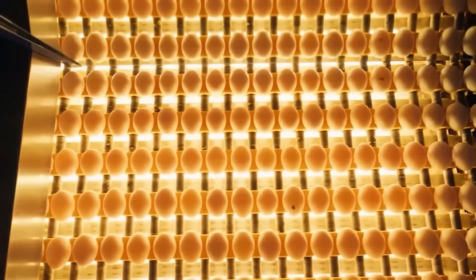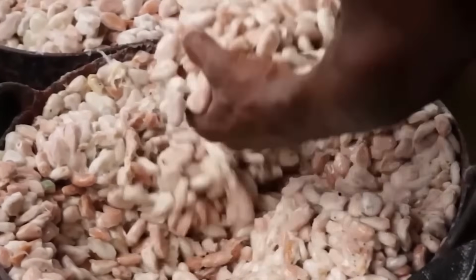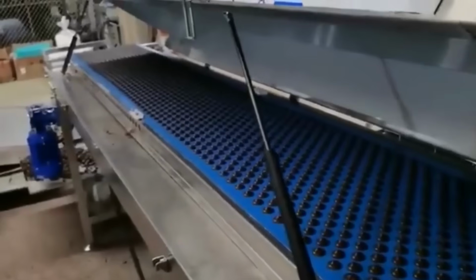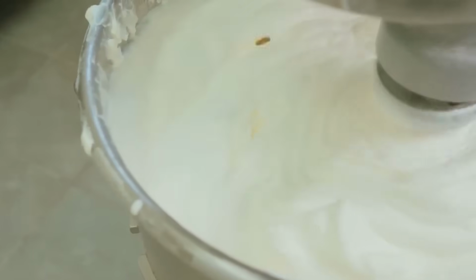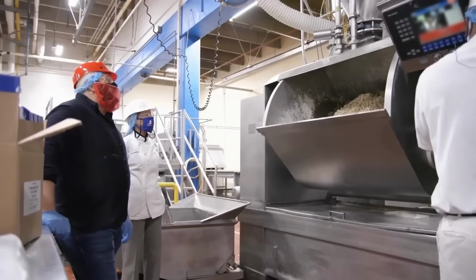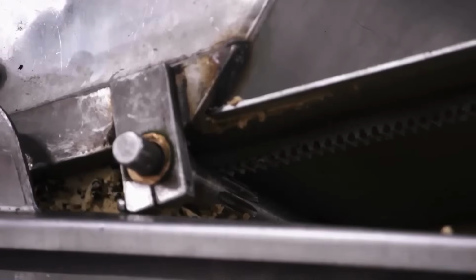Secondary packaging lines aggregate cartons into shipping cases. Cases are erected from flat blanks, filled automatically, and closed with either glue or tape depending on distribution requirements. Completed cases are printed with pallet codes, production timestamps, and destination routing labels. Automated guided vehicles, AGVs, or roller conveyors transfer cases to palletizers. Palletizing robots layer the cases using defined stacking patterns optimized for pallet stability and load efficiency.